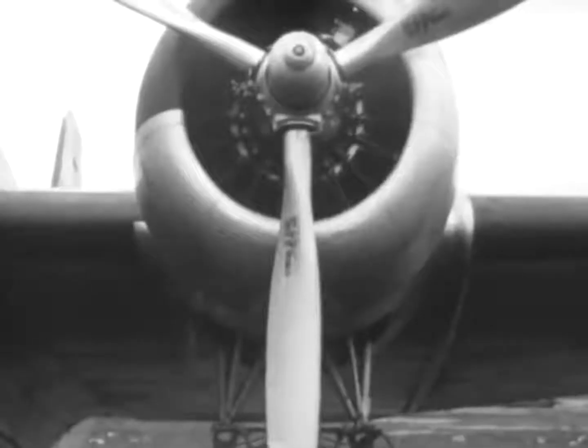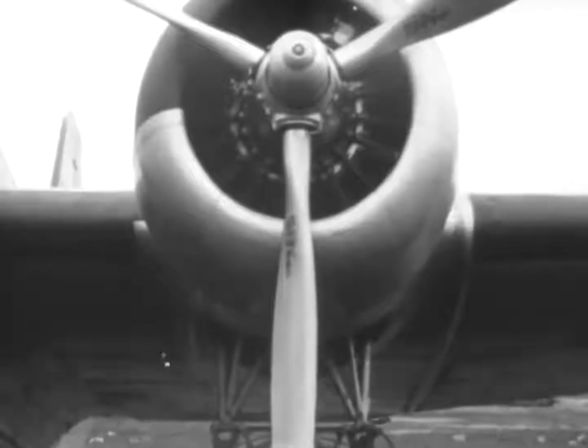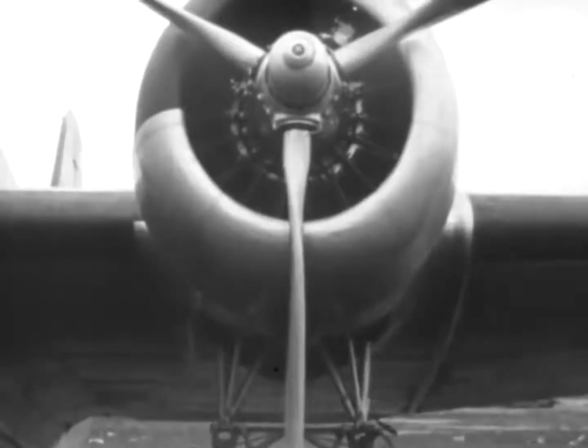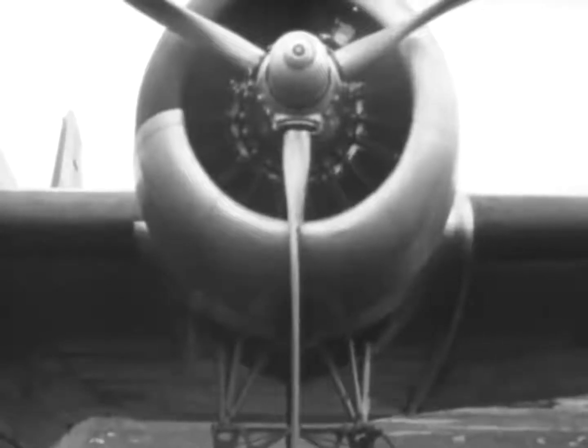Many medium-sized and large multi-engine aircraft are fitted with Hamilton hydromatic propellers, which have the additional property of feathering. In case one engine fails, that propeller must be capable of feathering, or turning its blades straight into the wind. For clarity, feathering is shown with the engine stationary.